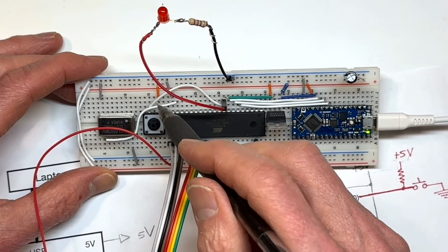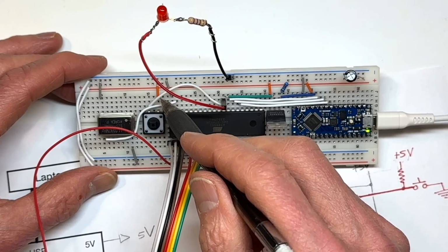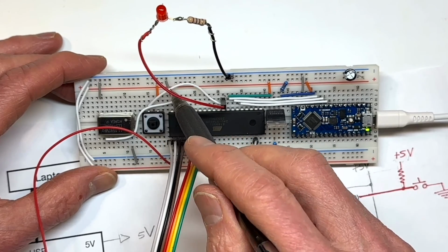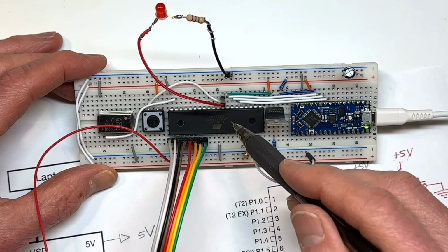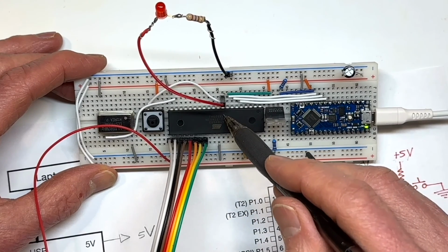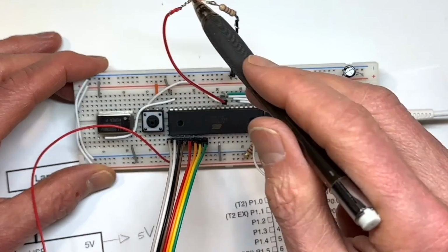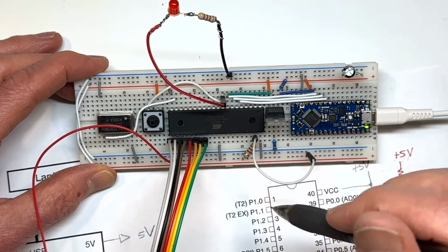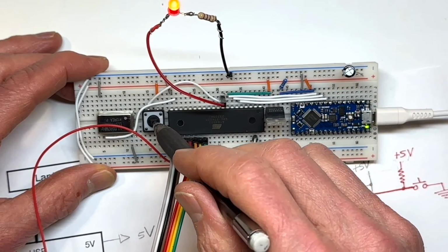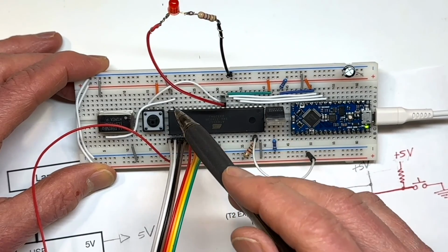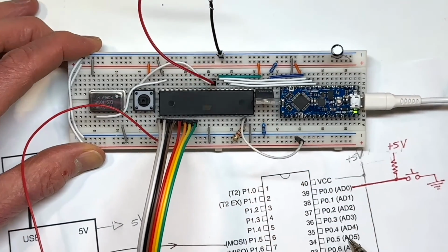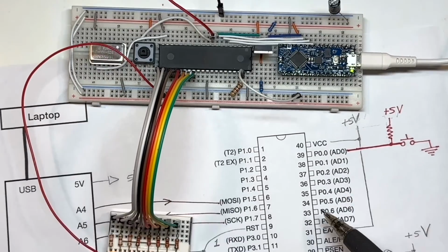Here's the push button switch, and it connects power, and through this white wire here it goes to pin 9, the reset pin. I've also got an LED across the reset pin, so we can test that here, and you can see that the reset pin works. Let's see, what else do we have for the 8051?